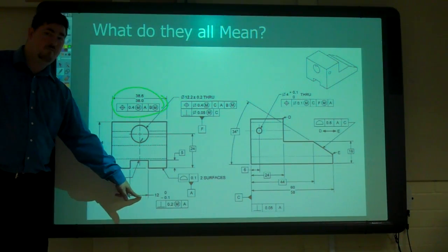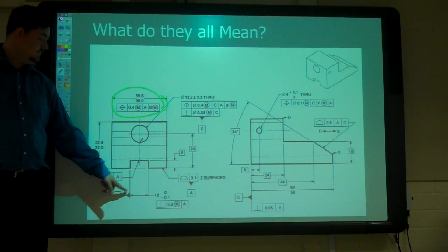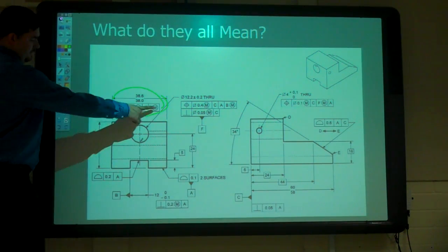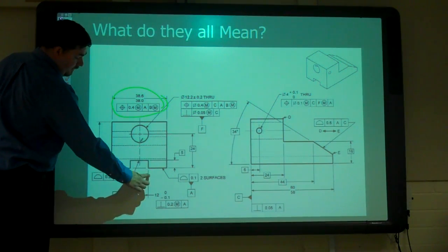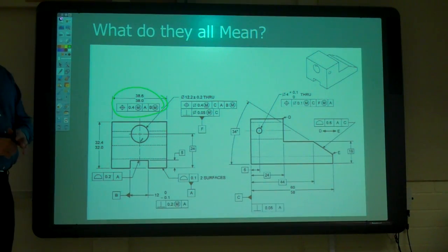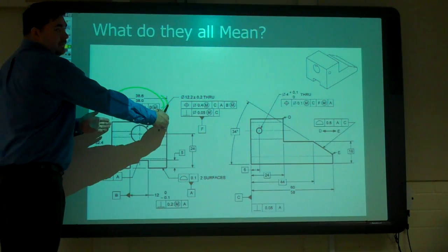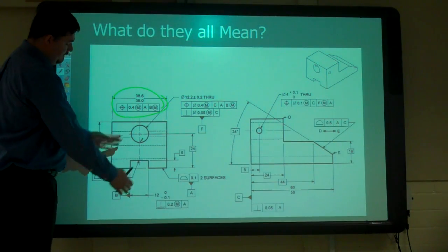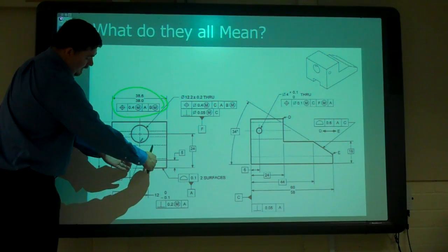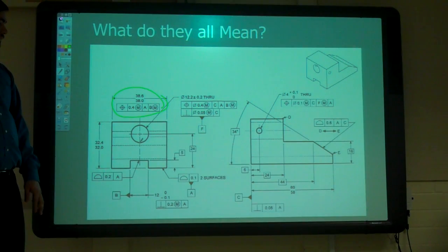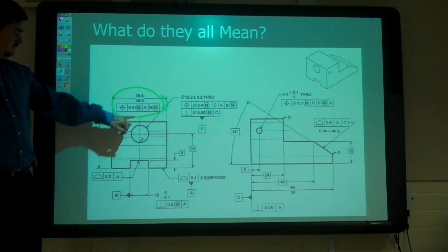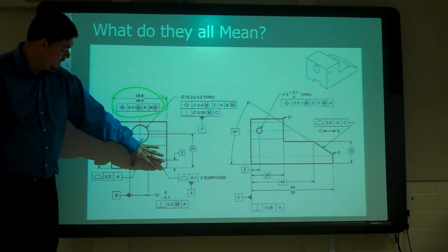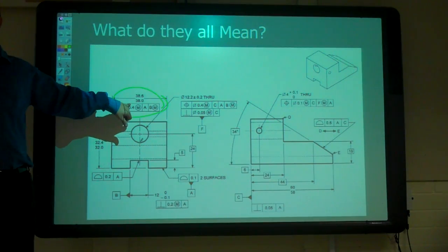What does that mean? So it's equal to the center, right? Center line. Just like this one is the center of this part, datum B is the center of that notch. So it's showing us the center line of this piece has to be positioned relative to the bottom and the center line of this piece. That's why they say line up A, B. That's why they got the M next to B, because it's still pulling off that same center line of the part. Just because when this changes, we want to be able to change the tolerance also.